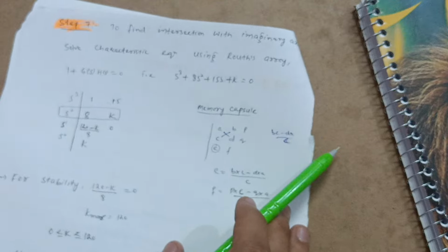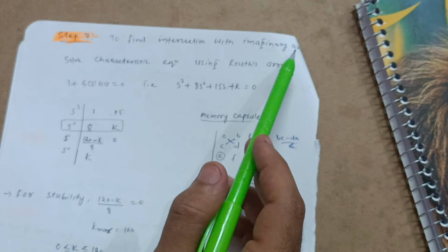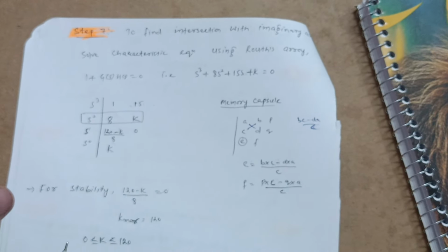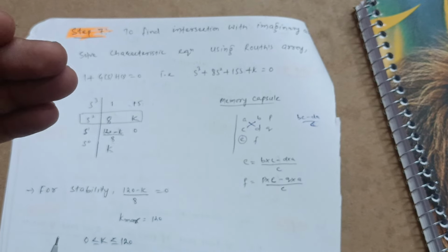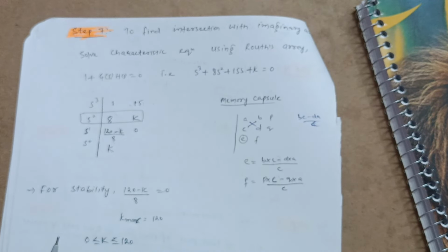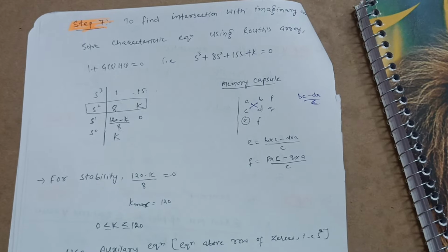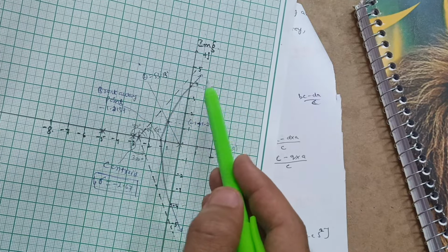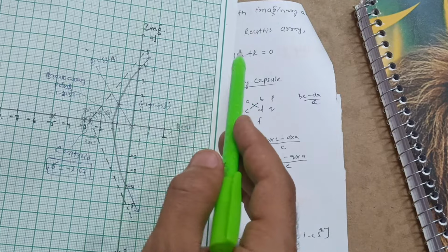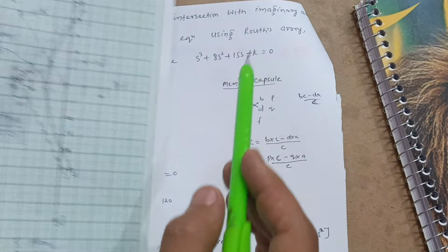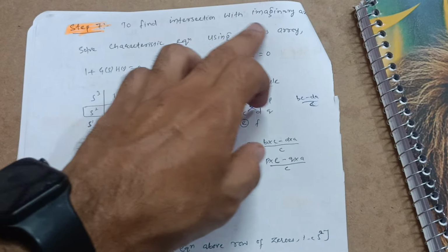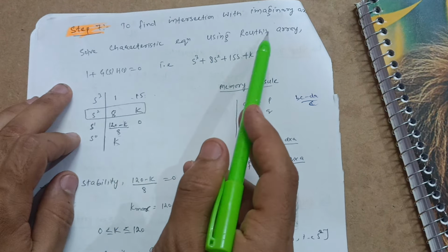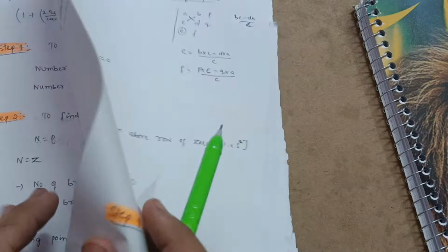Now the seventh step is nothing but to find intersection with the imaginary axis, that is the crossover point. You have to check, the branches start at poles. So whenever we proceed those branches to infinity, they will be crossing the imaginary axis, as in the graph itself you are seeing here. When this touches this imaginary axis, we have to check this intersecting point. So to find intersection with imaginary axis, solve the characteristic equation using Routh's array,